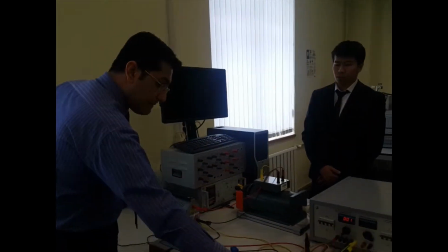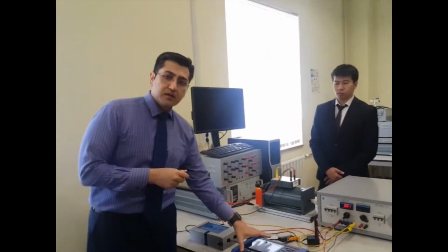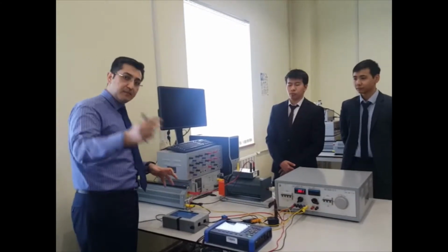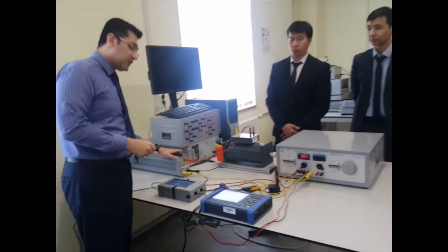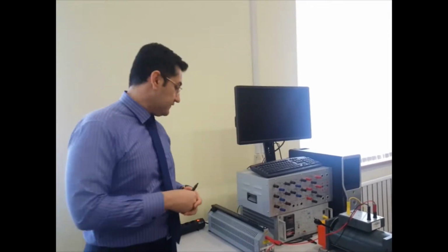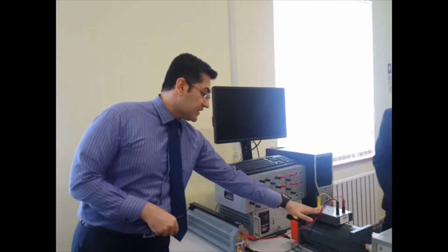To complete the setup, of course, we need to calibrate our device against a very well-recognized device, which is our power quality analyzer. Let me give you some explanation about the setup. We have a resistive load, which plays the role of a lighting load, assuming we are still using conventional lamps, because the new lamps have inductive and capacitive components. Then we put in the circuit an induction motor, which plays the role of an inductive resistive load.